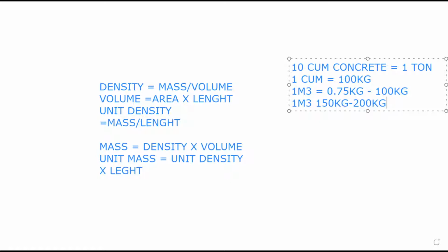Now, this is for nominal design, if you don't want to stress yourself. So your job is to calculate your volume of concrete. You translate it to tonnage of reinforcement. You now go back to the table I showed you. You now know how many pieces make up 1 ton for Y8, for Y10, for Y12, for Y16.